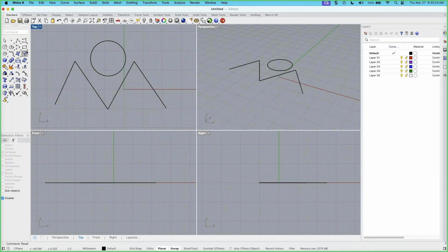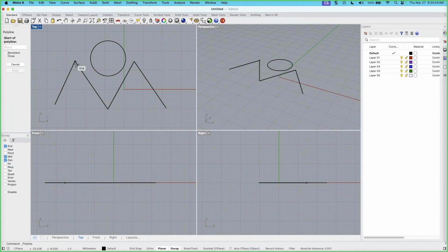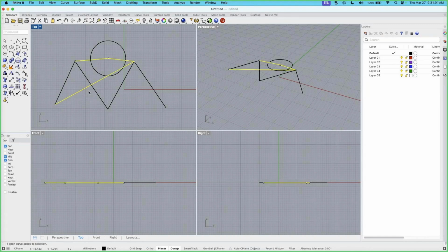Okay, so just be aware that your command line is over here. On the far left, you have the object snaps. The object snaps are point filters, and I typically have these three on. And the great thing about them, as I go to draw a line, they're going to snap onto existing geometry. Whether it's the center or the end point, that's what object snaps are used for. So accuracy, and very efficient accuracy.